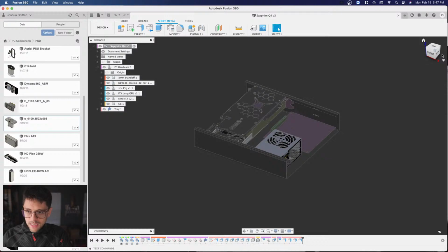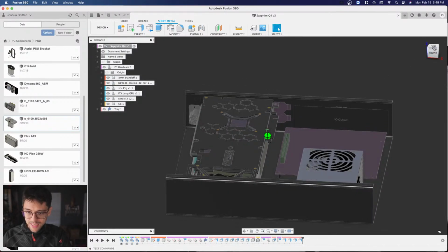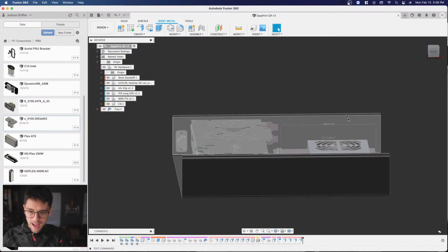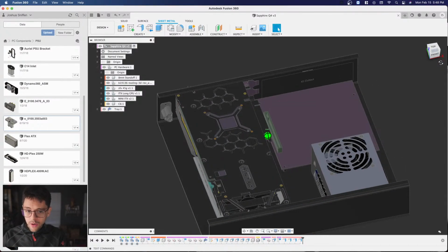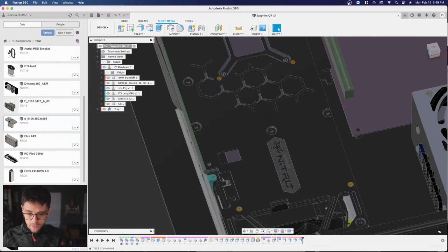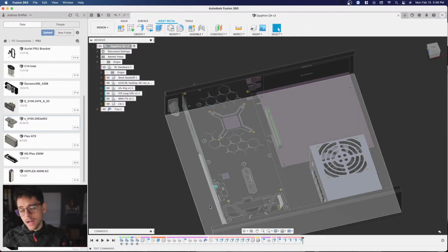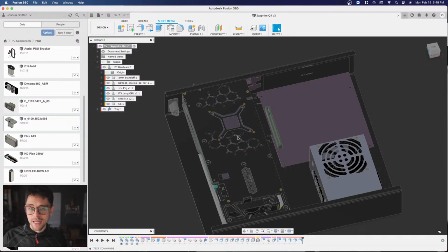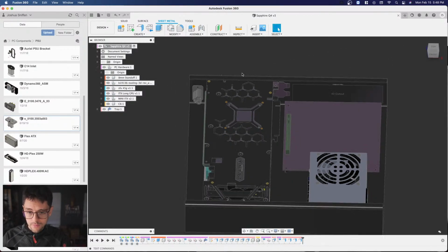Mr. Zeng asked me if I can put the C6 connector above the motherboard and if I would save some space. It won't fit with how much space I have here now, but certainly if I want to increase the height of the case, I could do that. The one thing I have to take into consideration, though, is the C6 connector is in line with the cables for the graphics card, which have to come out and bend down, and they're going to be sleeved. So I do need to have space for those anyway. So I'm not actually wasting any space by having the C6 connector on the back for this particular design.